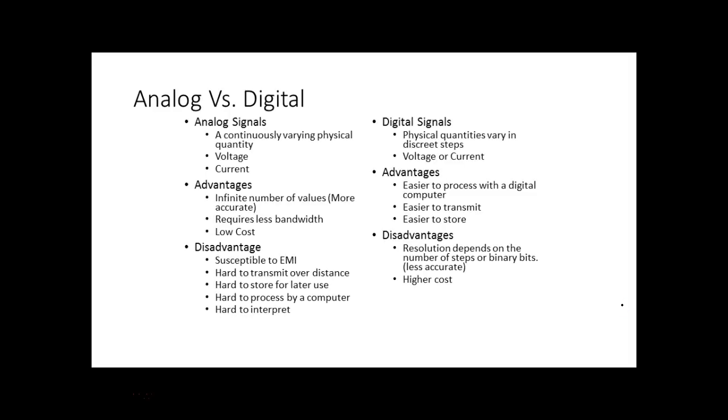So we have two categories of sensors. We have analog sensors and we have digital. Analog sensors, whatever quantity they provide, is going to be constantly varied, right? But it's usually going to vary between 2 points, especially if you're using a voltage level. The minimum voltage you could get if we use a 5-volt supply would be 0, right? You understand? And then the maximum would be what? 5 volts. But what's nice about analog is that it could literally go through an infinite number of combinations between 0 and 5.